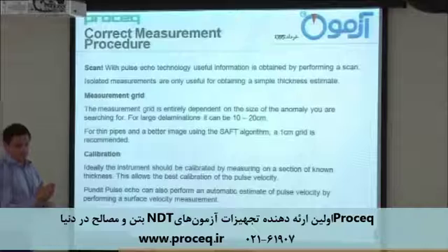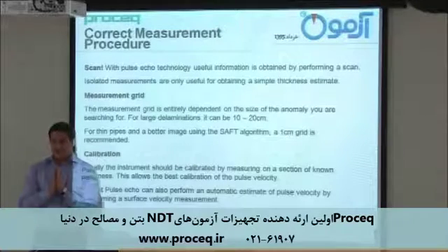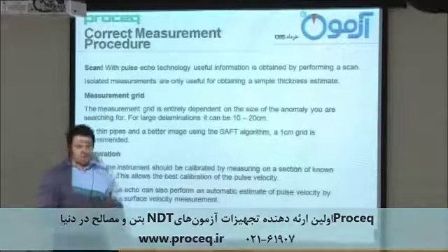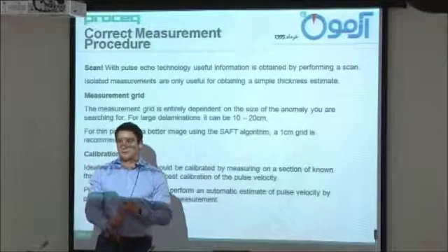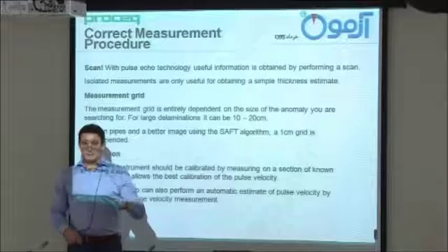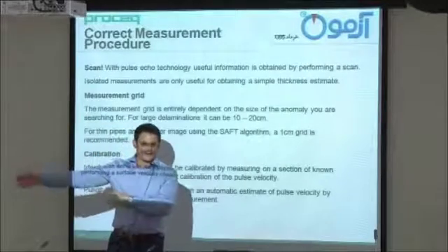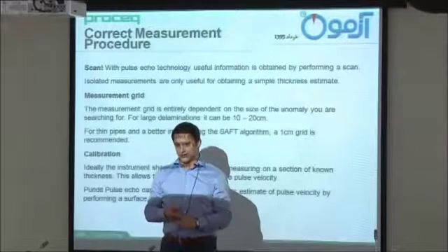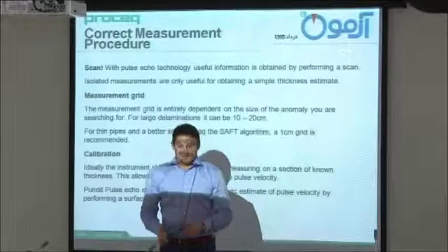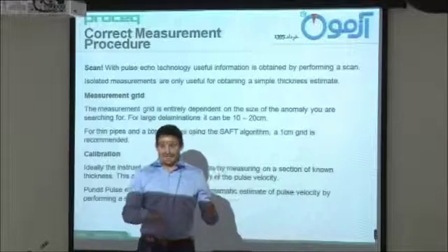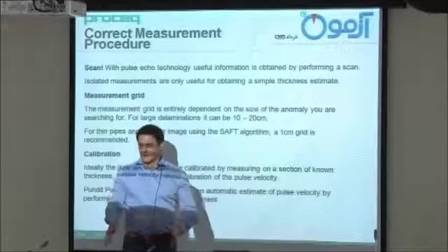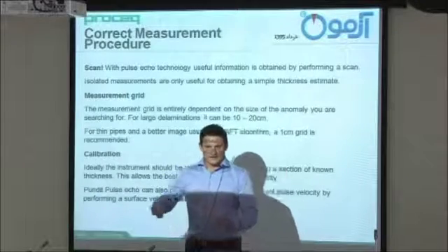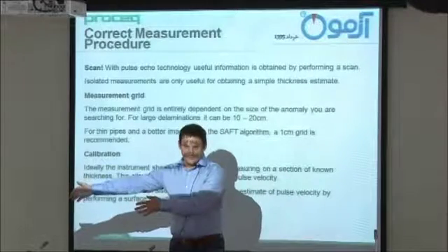Calibration, as I have said, please do it on site. On site in the concrete you will have rebars. You will see this is exactly the concrete. When I'm home, maybe I have in the office, in the laboratory, maybe I have perfect concrete, maybe with not so many rocks inside. So I get the different calibration. Do it on site. Those 5 minutes to 10 minutes will save a lot of wasting time if you did it wrong.